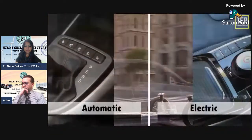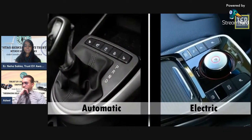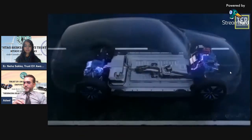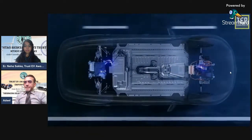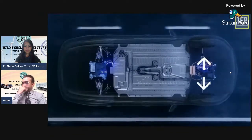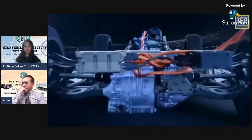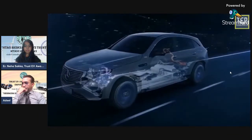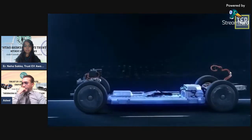Electric vehicles are like an automatic car. They have a forward and reverse mode. When you place the vehicle in gear and press on the accelerator pedal, these things happen. Power is converted from the DC battery to AC for the electric motor. The accelerator pedal sends a signal to the controller, which adjusts the vehicle's speed by changing the frequency of the AC power from the inverter to the motor. The motor connects and turns the wheels through a cog. When the brakes are pressed, or the car is decelerating, the motor becomes an alternator and produces power, which is sent back to the battery.